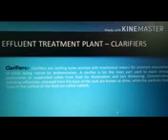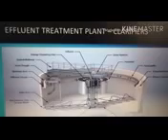The clarifier picture clearly shows the influent and energy dissipating inlet, grated walkway, scum skimmer arm and effluent, rake arm and 304 stainless steel scraper blade, support columns and a dry platform, feed well and scum baffle, V-notched weir, effluent launder and sludge discharge pit.